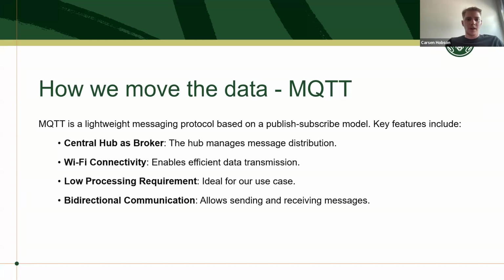Yes, so over the network, we can use a messaging protocol called MQTT. It's extremely lightweight, so not computationally heavy on the Raspberry Pis, which is exactly what we need. The central hub, the main Raspberry Pi, acts as the broker, and distributes and receives messages.